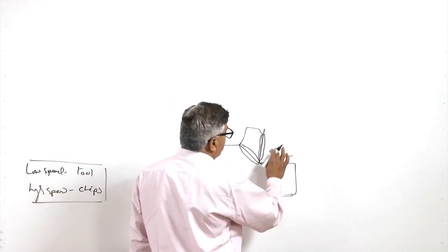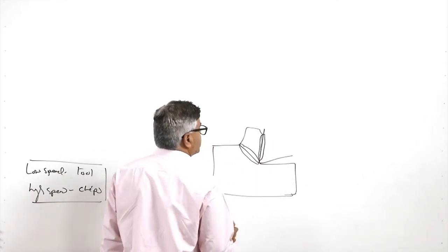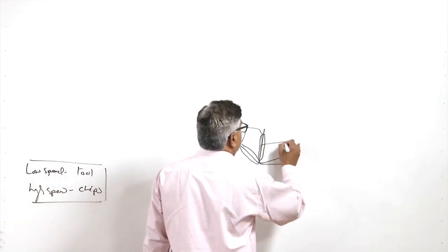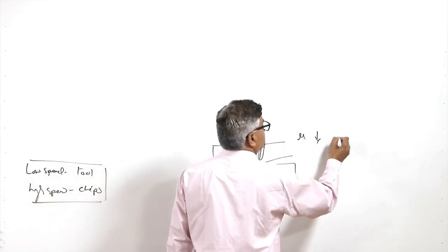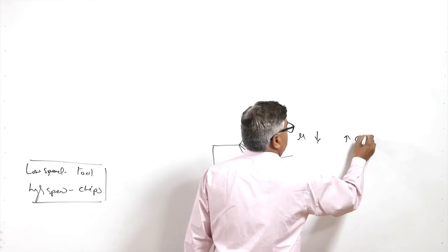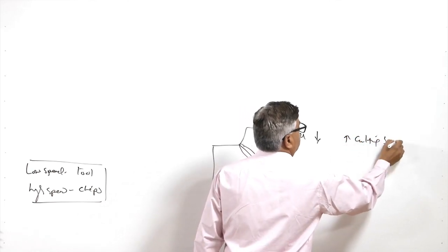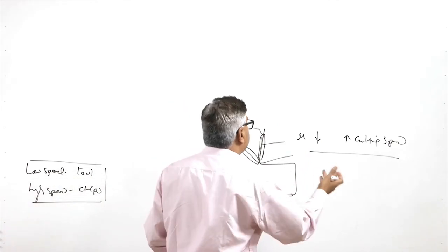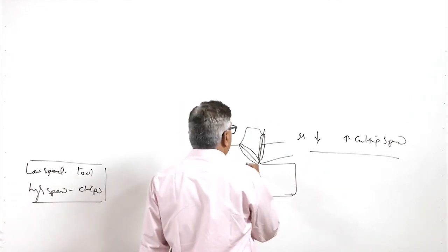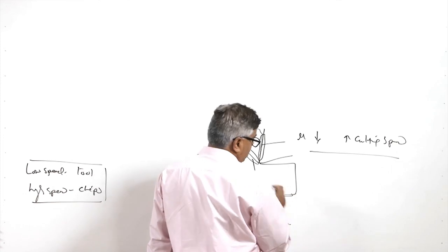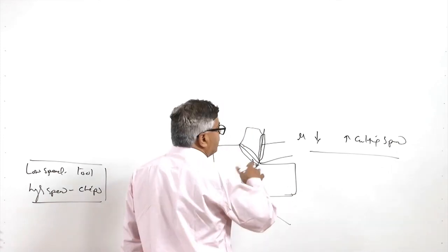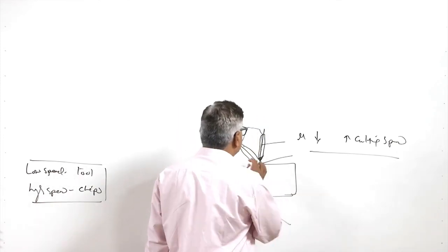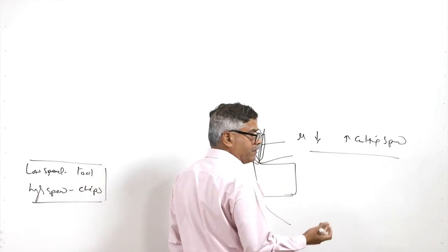Considering that there is no rubbing between the tool and the workpiece, the friction actually decreases with the increase of the cutting speed. So, the frictional heat should reduce with the increase of the cutting speed, and unless there is a negative rake angle, speed will not be having much effect on the shear deformation energy required for shearing.